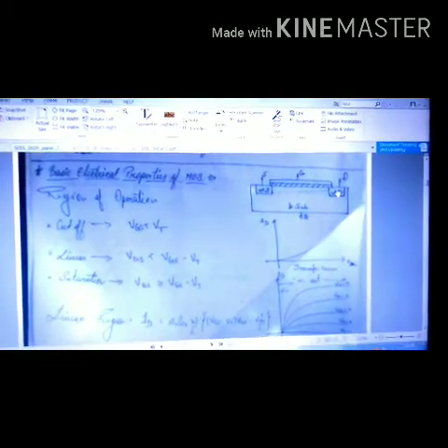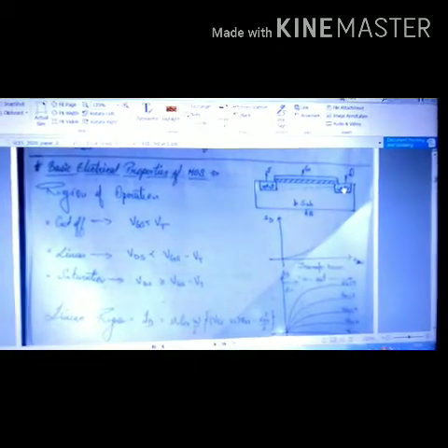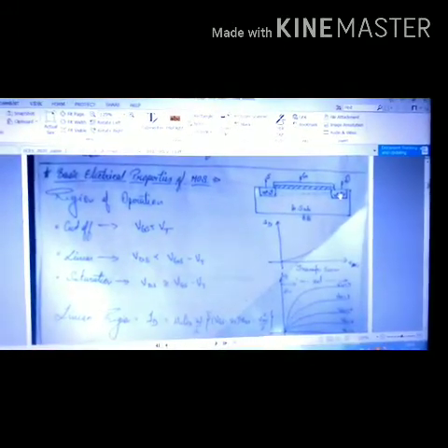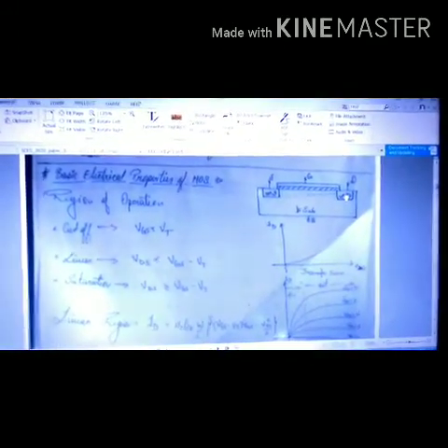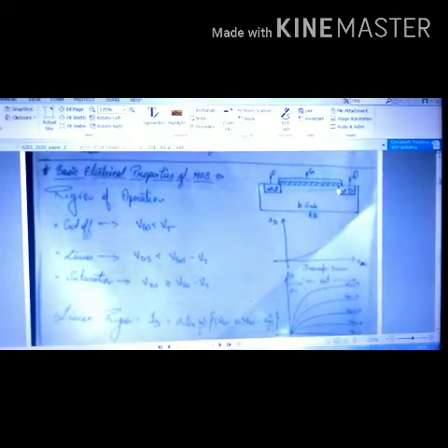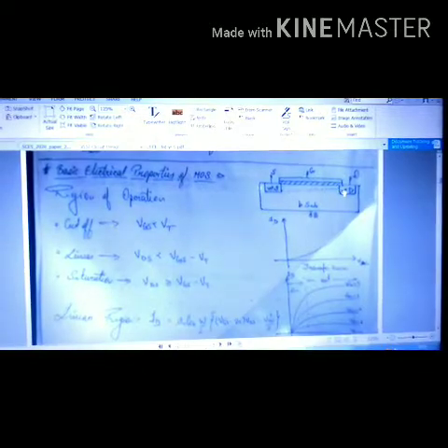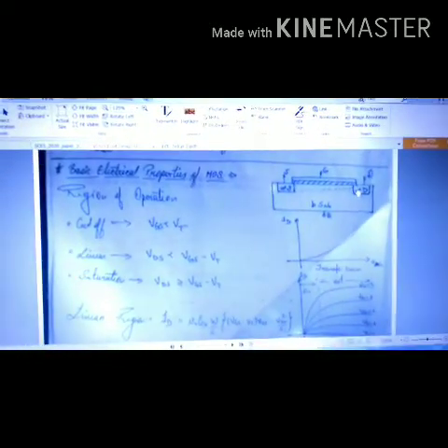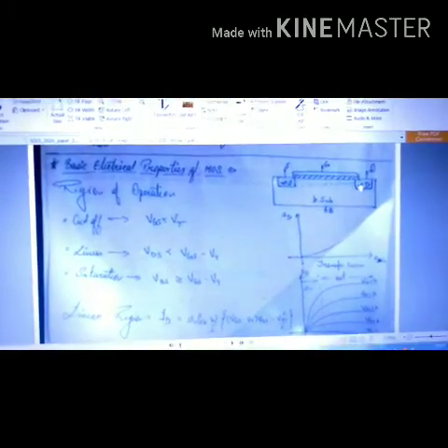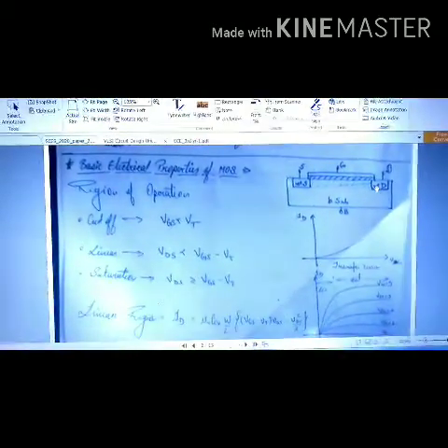Now why does the current flow in the device at this time? Because the voltage is so high that electrons gain enough kinetic energy to pass this small depletion layer between the channel and the drain terminal, and they enter the channel anyway, which causes a good flow of current.